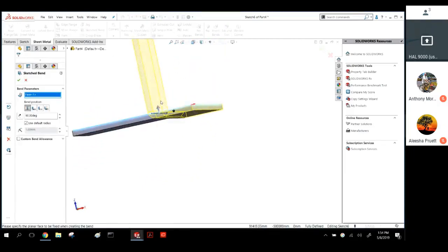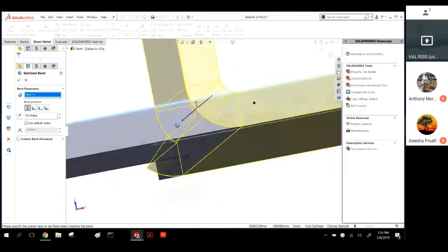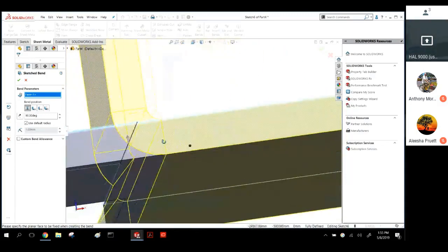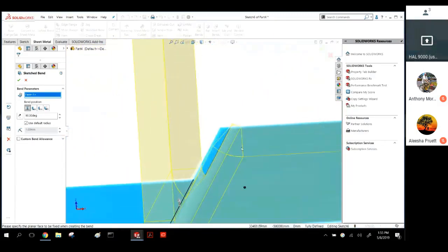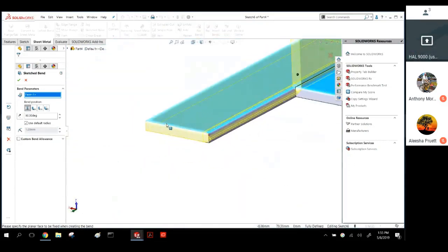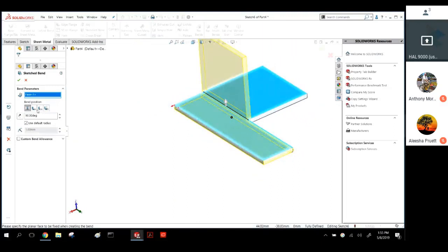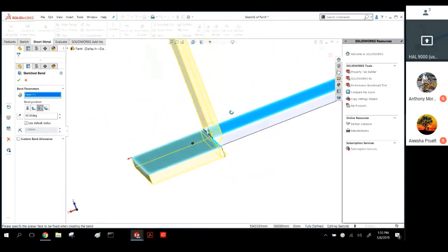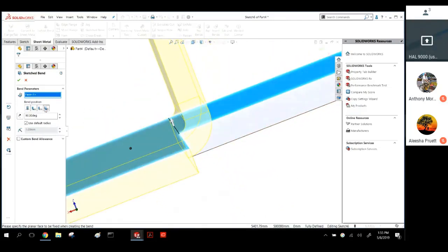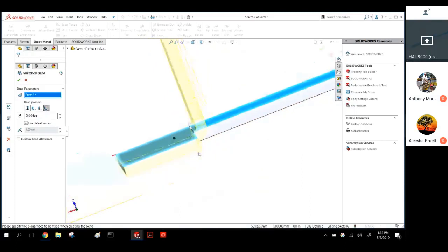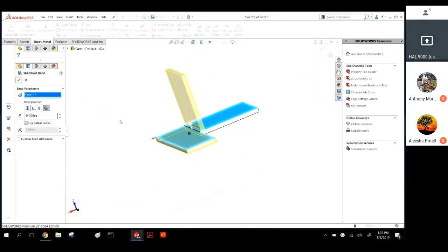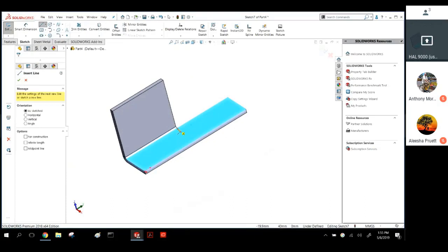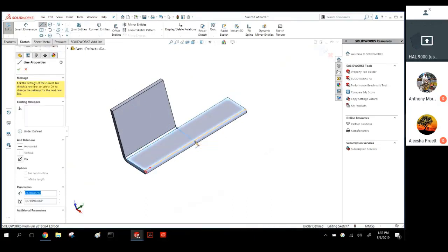Now, before I was hitting do it at the line, but that's going to be problematic here because where that line is, the inside bend radius is making it so that it's bending this edge of the part, which is typically not what you're after. If I go to the inside, it only gets worse. If I go to the outside, better. Still starting to kick up this area. If I go this next one, that's one bend radius out. And then I don't accidentally tear that corner up. But that's a common mistake people will make.